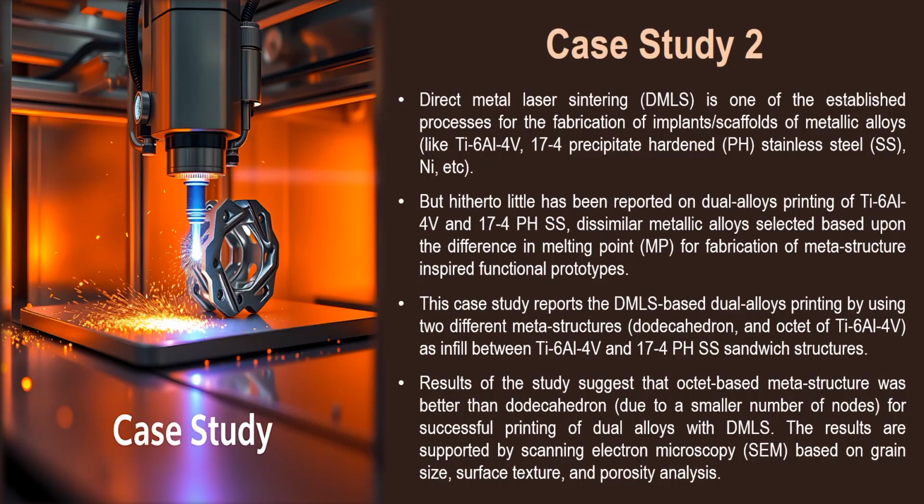So what we do in this case is use two types of metastructure. One was dodecahedron and another was the octet. And the study suggests that the octet-based metastructure performed better than the dodecahedron. The reason is the smaller number of nodes.